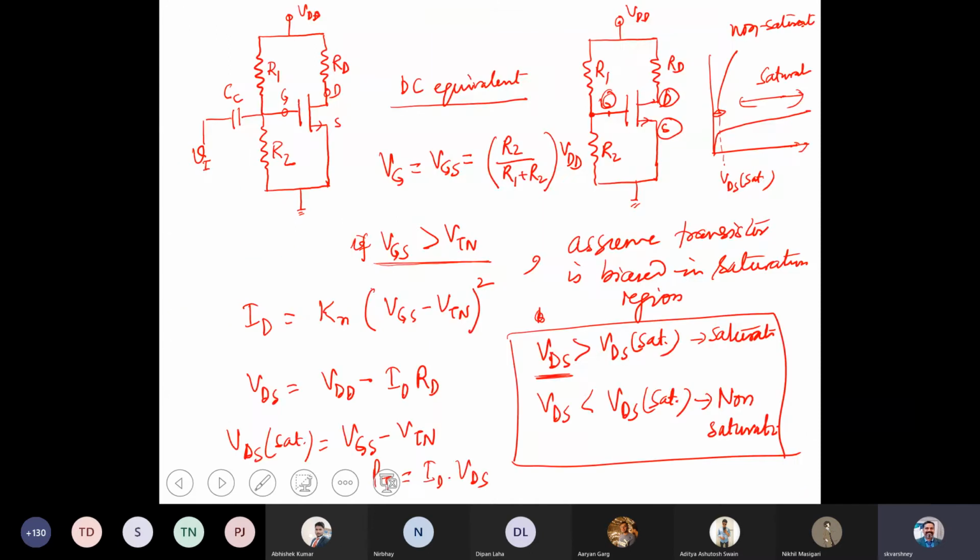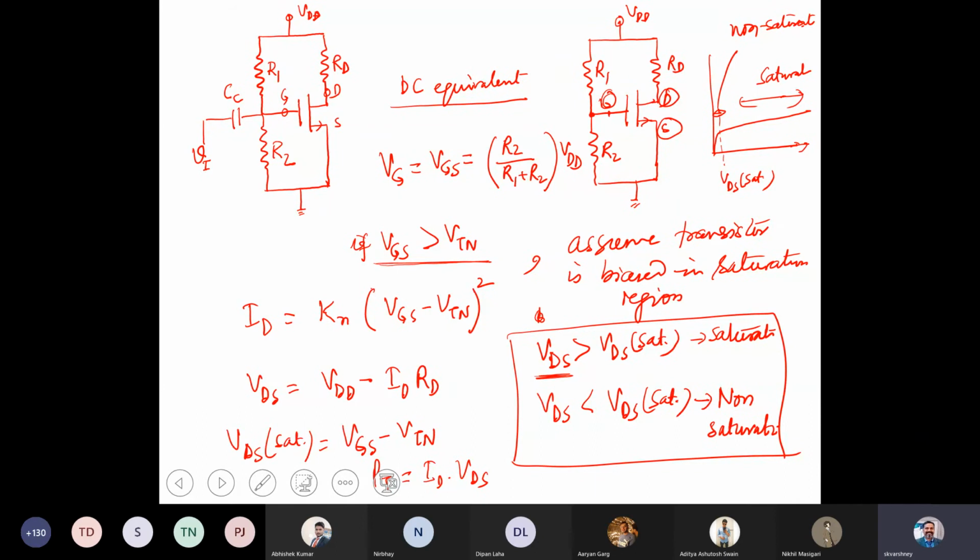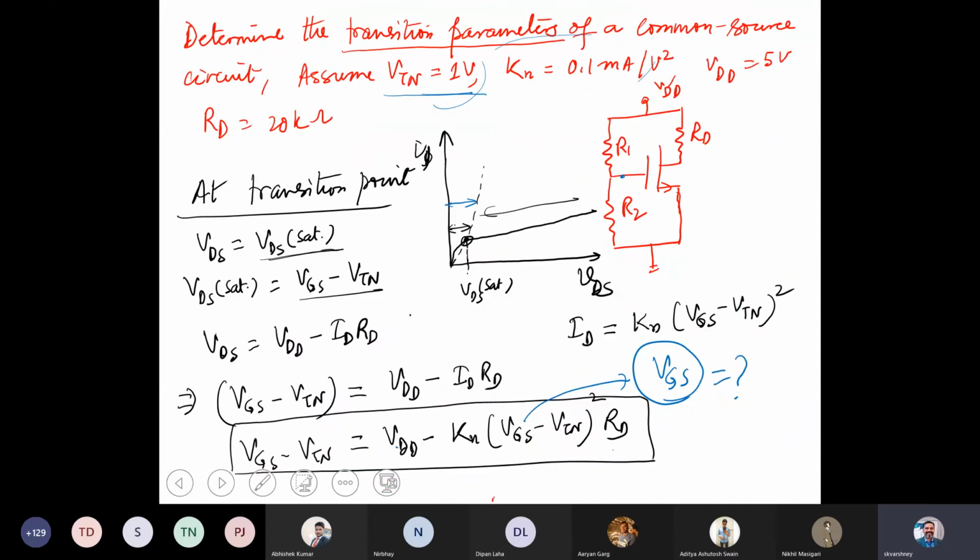So that's the reason we have the voltage divider circuit, because the gate voltage at this point can be controlled with the combination of R1 and R2. Right, so I think you can estimate this value.